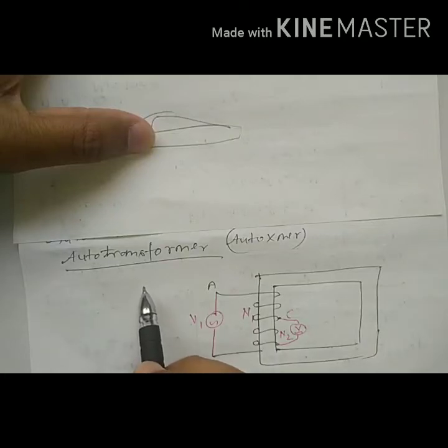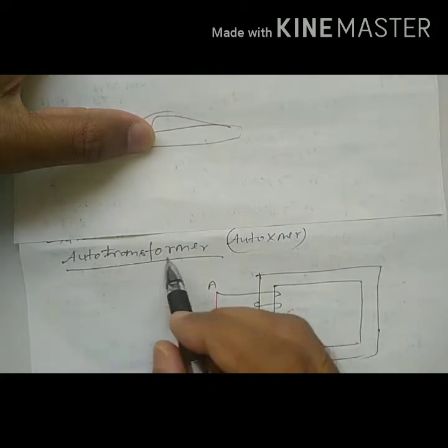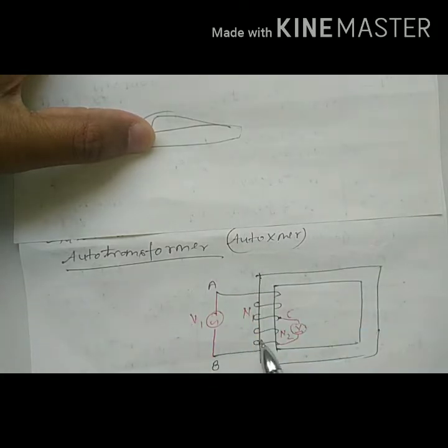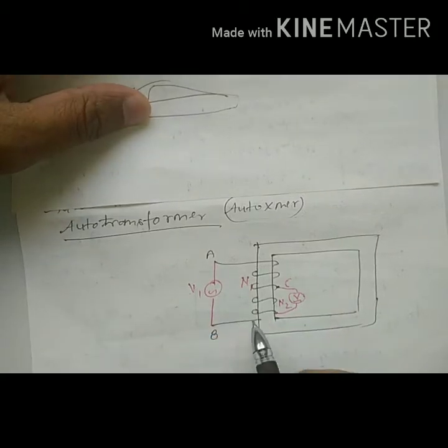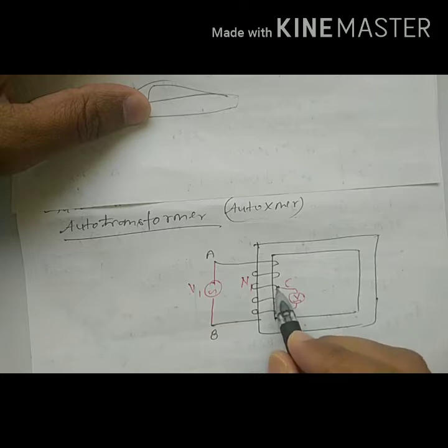Let us see the last topic of this unit, that is autotransformer. I will write autotransformer like this. This is a core and we are applying only one winding on this limb, right? So if I take two wires from any point, say this point is C point, and here a tapping, from here and from here I took a wire, so here the number of turns will be different than the total turns.